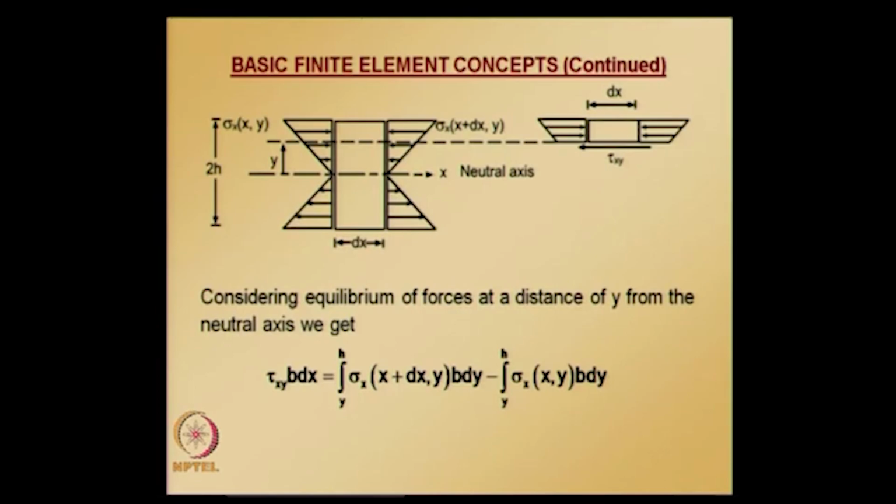So, this is what was mentioned earlier. The computation of shear stress is obtained by finding the unbalanced normal force and equating that to the shear force.